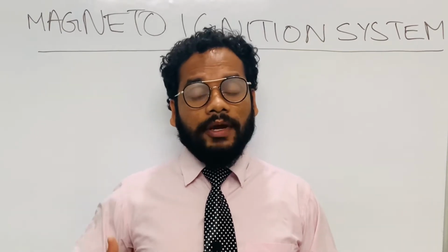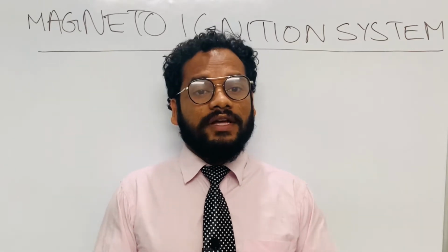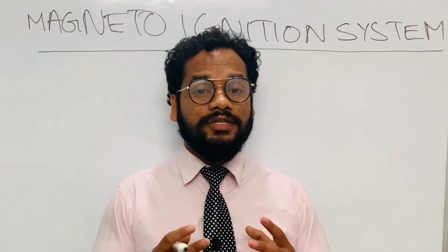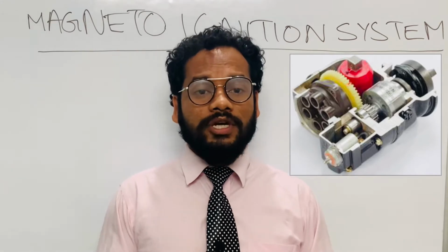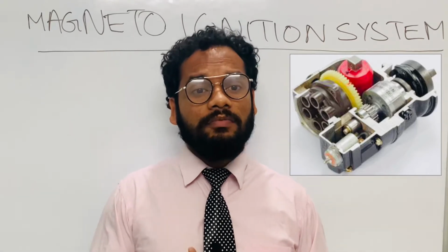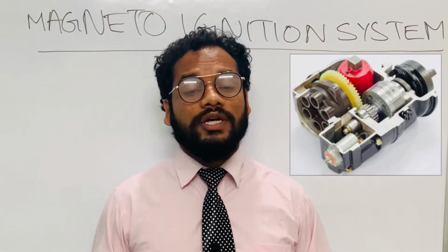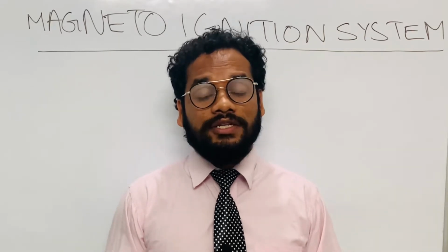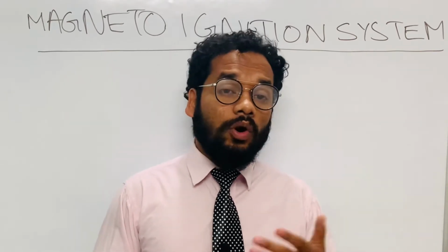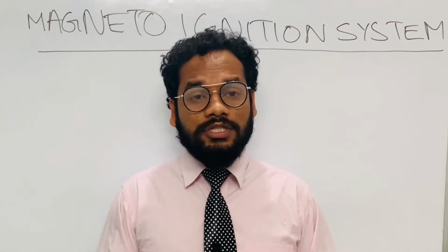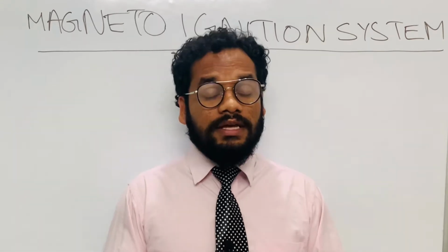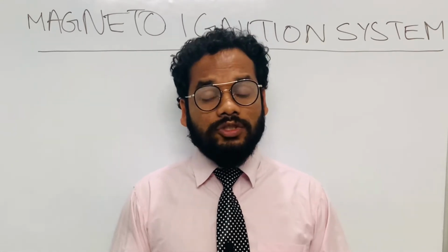Magneto ignition systems can be classified as high tension or low tension. These consist of some principal components contained within the magneto itself, basically a combination of a permanent magnet, AC generator and an auto transformer. Of the two, the high tension magneto ignition system is most widely used. The requisite alternating fluxes and voltages can be produced by rotating the transformer windings between the poles of a permanent magnet. In such a case, the magneto system is classified as rotating armature.